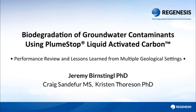The blocking of a formation through microbial growth typically will not occur unless we're looking at a point source of microbial growth, say around an injection well that's putting in a high bioavailability electron donor such as molasses or lactate or whatever it may be. Dispersed into the formation, the microbial growth typically does not change the permeability of a formation, as we know from all of the ORC and HRC and other projects that we've done over the last 23 years or so.